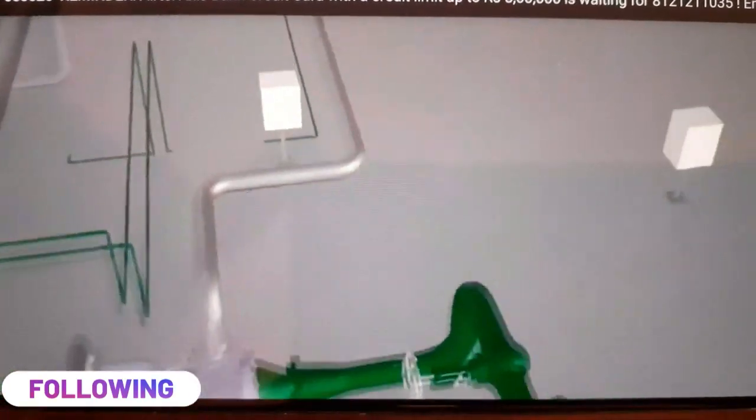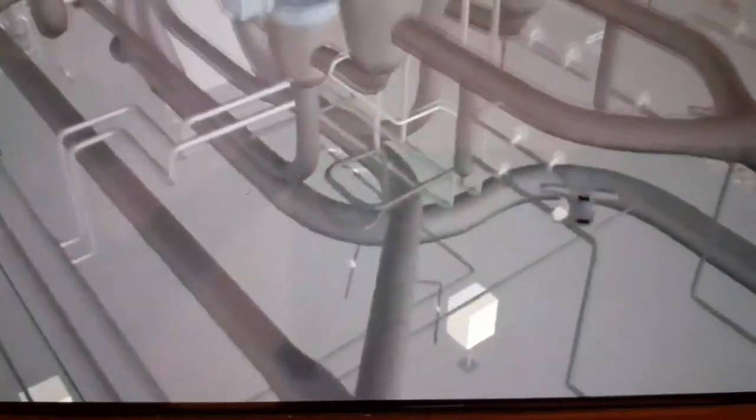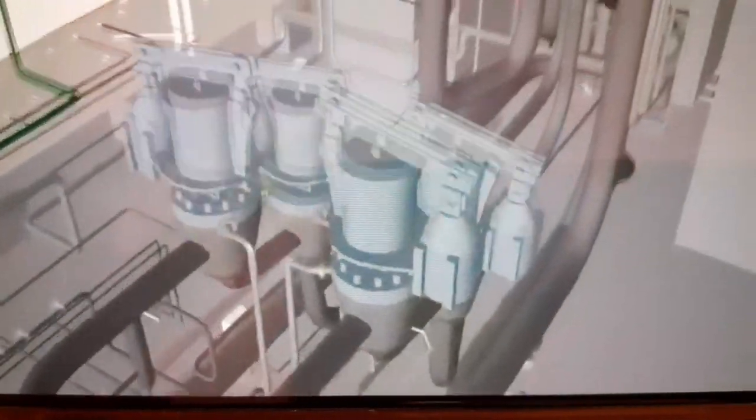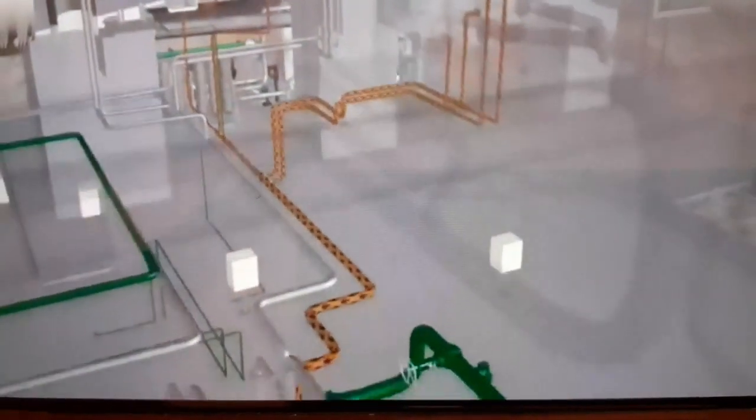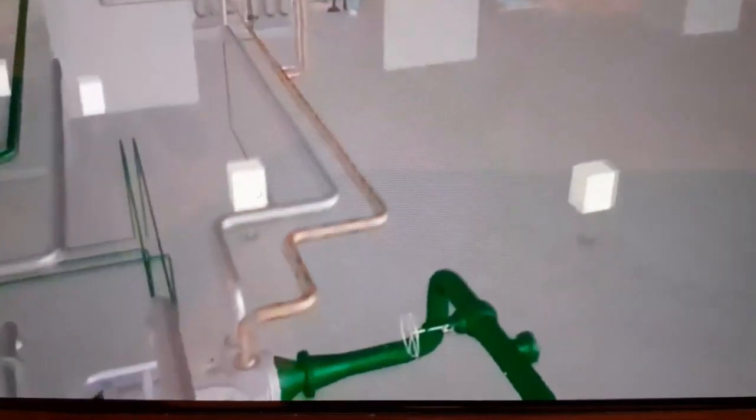The gland steam system also accepts leak-off steam from the main steam stop valves, main steam control valves, reheat steam stop valves, and the reheat steam intercept valves. This leak-off steam is routed to the gland steam condenser.